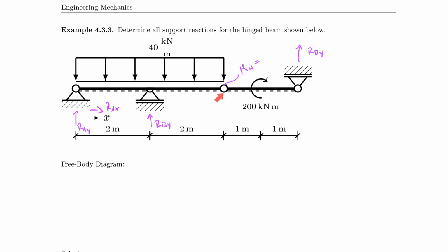And now I would be able to solve them, and in this case it actually doesn't matter what you do. There are 2 easy ways to solve this. The easier way, of course, is what you probably are thinking of: you release this part of the system and you find equilibrium. That would definitely be what I would be doing in an exam. But just for the concept, let's talk about the fact that you can also release this part of the system and find equilibrium about this point.